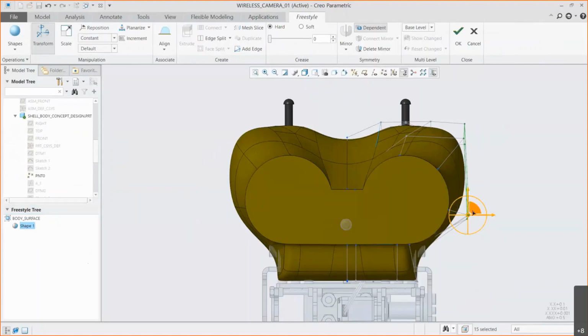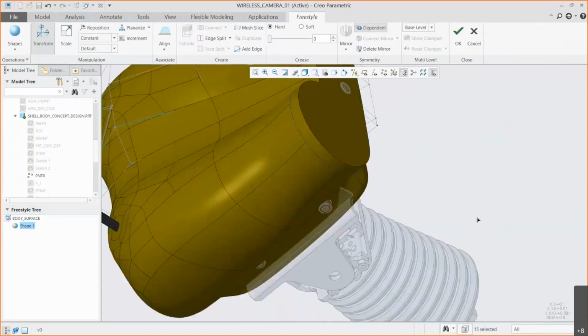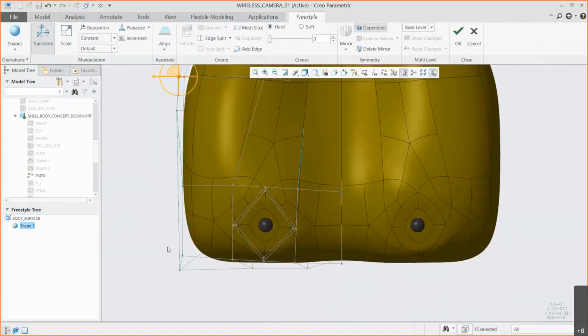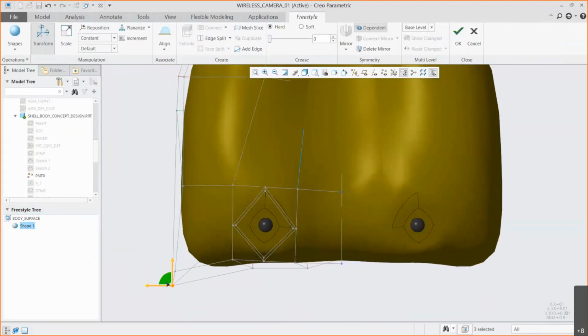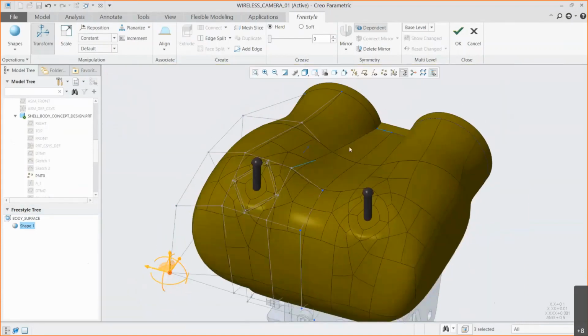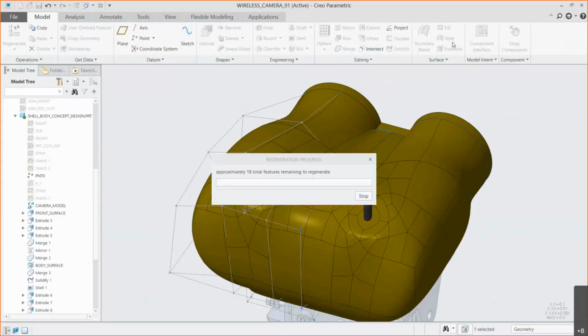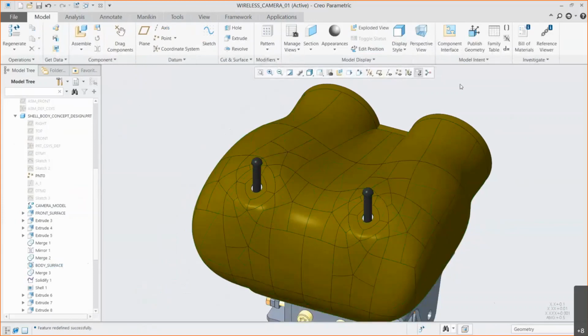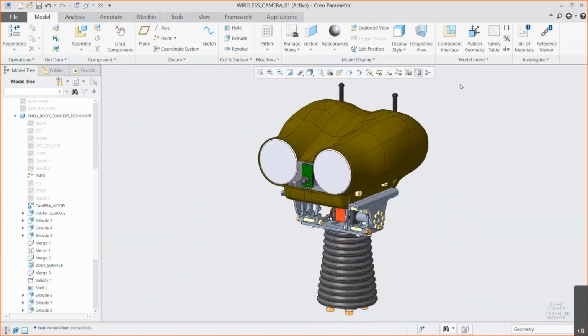This right here that you see, this is the freestyle modeling tool. This is actually a tool that's as embedded in Creo as the parametric modeling tools that I'm sure everybody's familiar with. But this is our subdivisional direct editing tool, where you start with a primitive shape, a sphere or a cube, and then you add these nodes, and you can push and pull on them to get them into the shape you want. So this is really great in a lot of different use cases. One, you have this great organic geometry without needing any kind of surfacing tool or experience in surfacing. So that's a really great way to use this.